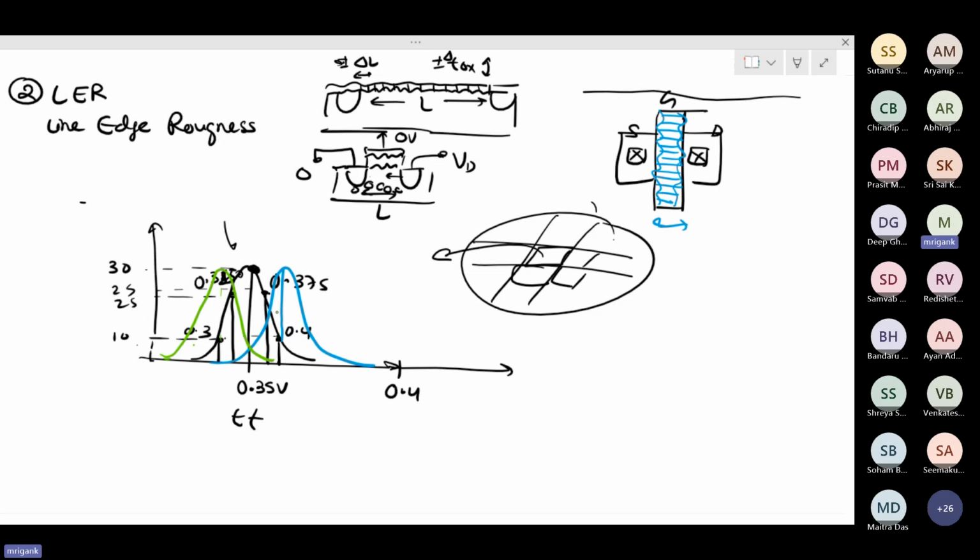So these concepts are very important in any practical circuit design. You need to be aware of both these process corner as well as random variations. Especially in analog circuits, it is much more important because whatever amplifiers, circuits, filters, differential units we are building, it assumes perfectly matched devices. And then in the actual circuit, we have this kind of variation. So both the process as well as the random mismatch need to be taken into account while designing practical circuits.